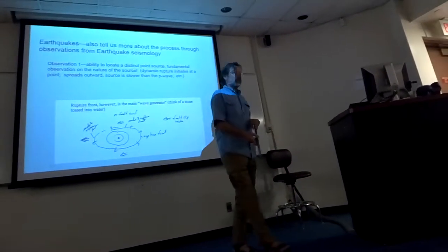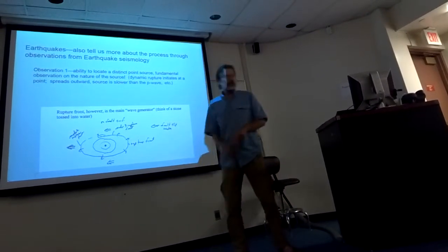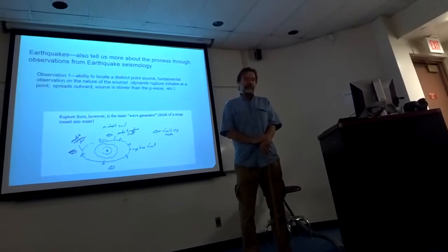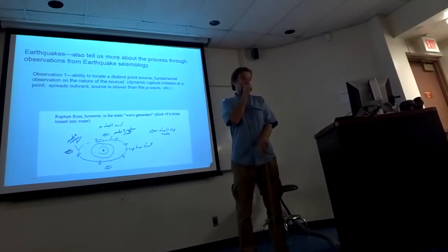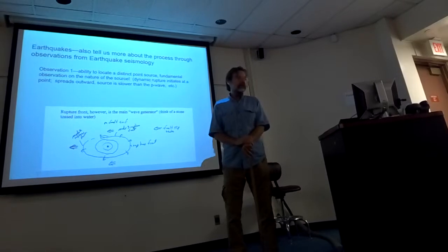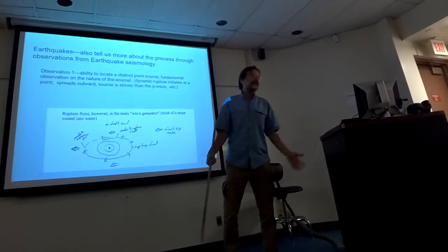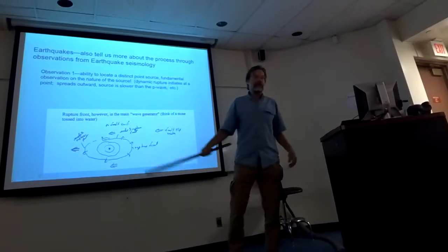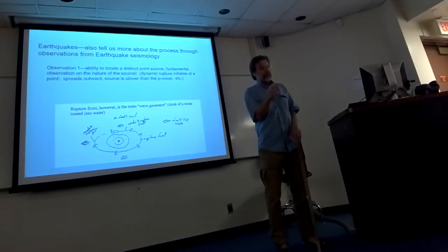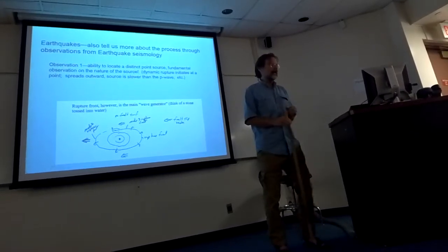That also might tell you why really big earthquakes last so long. If that front is moving at 3 kilometers per second, and it's a 1,000 kilometer long rupture, you can do the math, it's going to be a while. It's like several minutes before the event's over. And in fact, that's what events like Japan or Indonesia were like. They lasted 3, 4 minutes. That's why people always say they think the world is ending. Think about how long 3 to 4 minutes would seem when the whole world was shaking and you can hardly stand up. But anyway, that's a little off the point. The big point is that it's consistent with this idea of the rupturing of an asperity, or a strong spot on the fault, that breaks and propagates outward, a dynamic rupture.